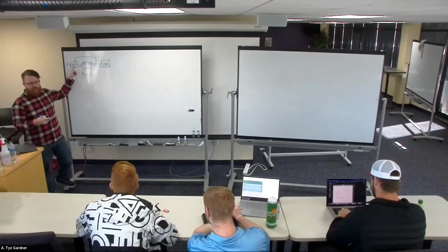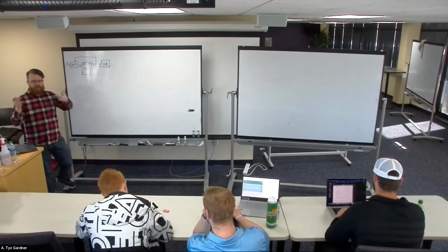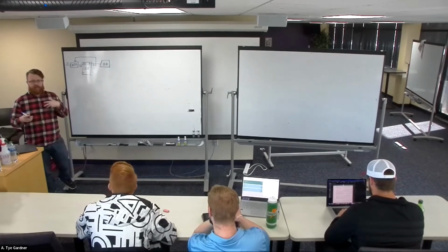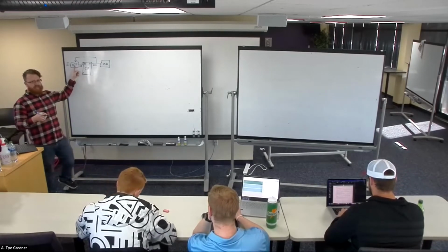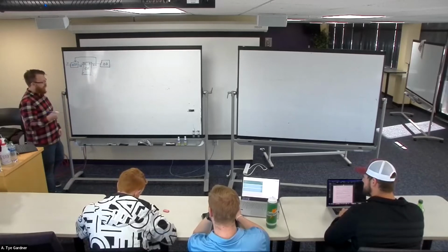State, because we have to know where we are to know where we go next, right? If this is a counter state machine, we can build a counter as a state machine. I have to know that I'm currently at the number 5, so I can tell my next state decoder to go to the number 6, right? You can do that. It'd be clunky, but you could.